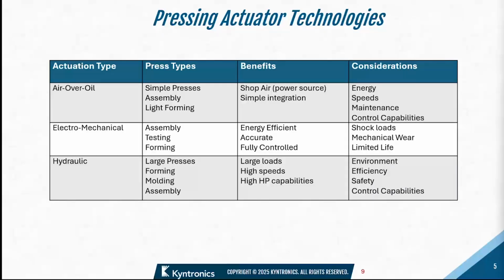Shock loads are an issue with electromechanical, as they're mechanical wear items. With that said, they all have limited life. And when that $10,000 actuator is done with its mechanical items, unfortunately, you have to throw it away and get a new one.